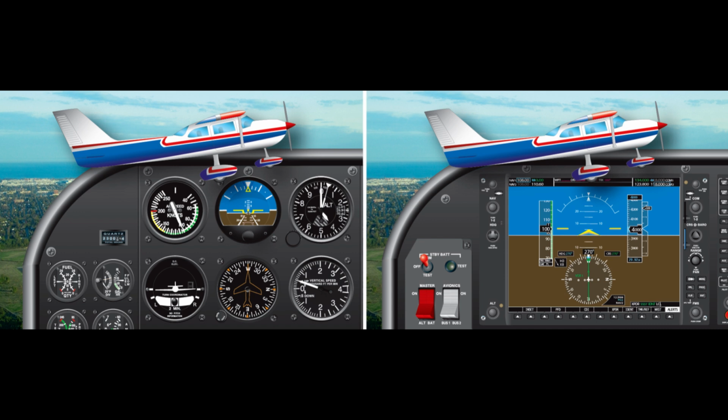pitch attitude. When a turn is coupled with a climb, the additional drag and reduction in the vertical component of lift need to be further compensated for by an additional increase in elevator back pressure. When turns are simultaneous with a climb, it is most effective to limit the turns to shallow bank angles. This provides for an efficient rate of climb. If a medium or steep bank turn is used, climb performance is degraded or possibly non-existent.